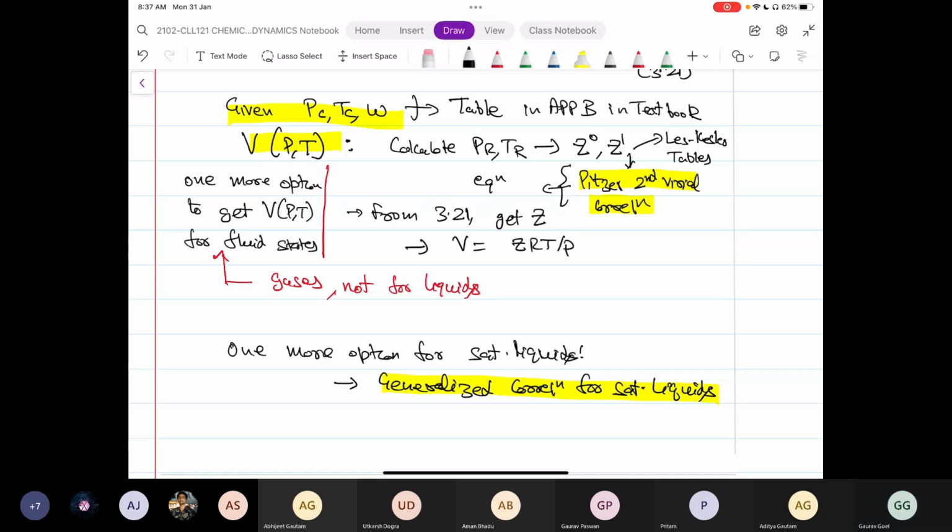If you want the most accurate information, either an accurate equation of state is required, or, as in the propane example, very accurate tabulated data. In that big data sheet I have shared, table 7 lists some of the liquid properties. This generalized correlation is one such expression, and it is not the same as Lee-Kesler.